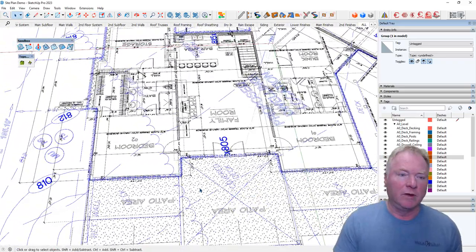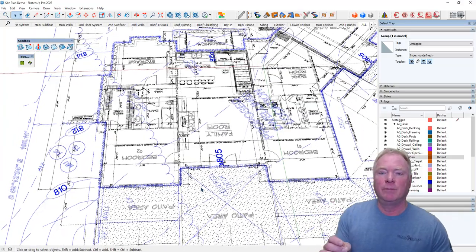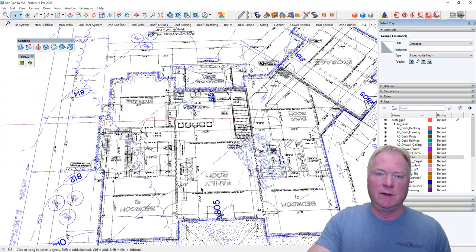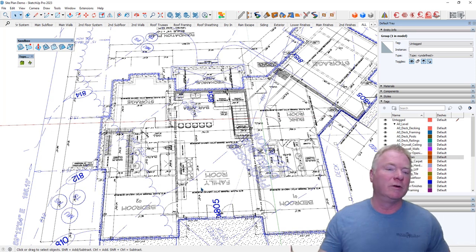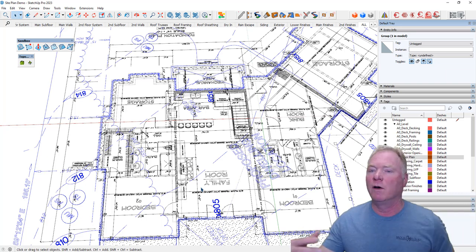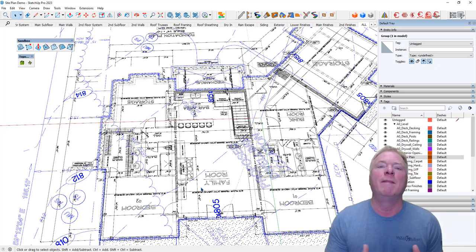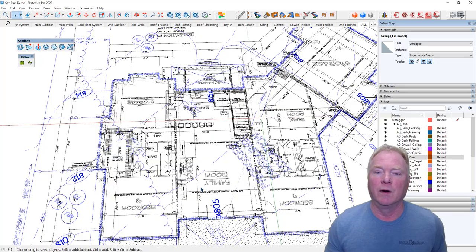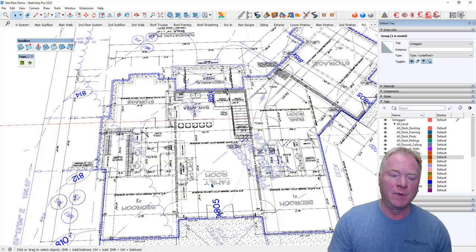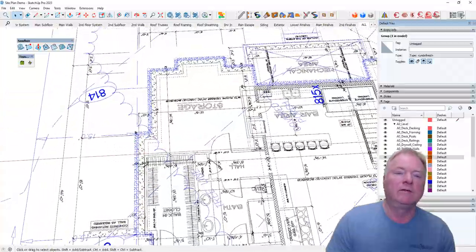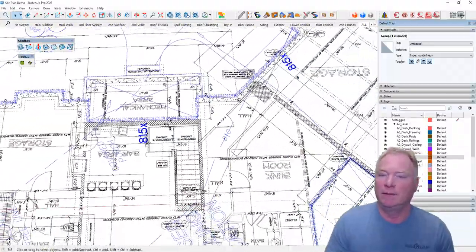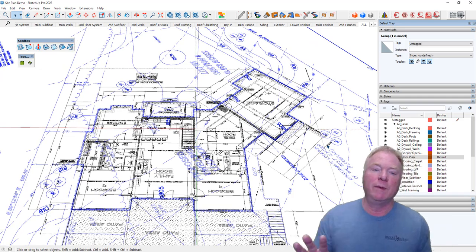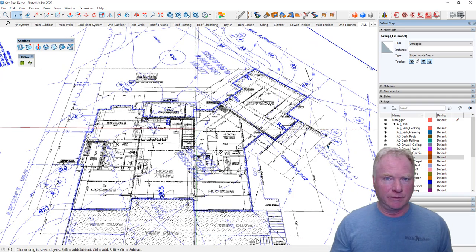Then I go around and I just look, because remember, a lot of times you're going to have a site person that's different from the draft person that did the plan. And sometimes they're changed. Sometimes the site plan was done, and then the architect makes changes, they extend a wall, they do other things, then things don't mesh. In a case you're going to see on here, I think some of the retaining walls they call for and some of the grades they call for aren't going to work. And that's the whole purpose of this exercise. So just in general, looking around, everything looks like it's hitting right, okay? And again, you have two different people that did this, so there's going to be chance for some errors.